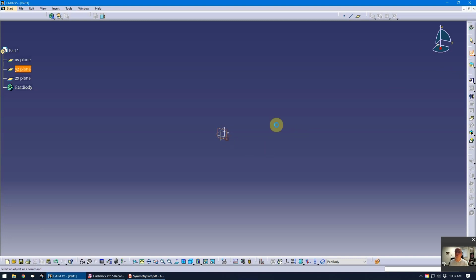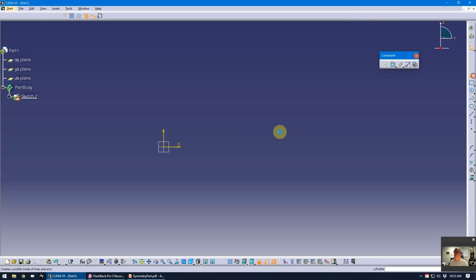I'm going to start a sketch here. The very first pad is going to be fairly simple, especially the sketch. I'm using the profile tool, and I'm capturing dimensional and geometrical constraints as I go through. I've got horizontal, vertical, horizontal, vertical. It looks like a coincident was established there. That's my geometrical constraints. As far as my dimensional constraints, I've got a length here, a length here, and then I also have a 120 right there. That makes my sketch green, which is what I'm looking for.